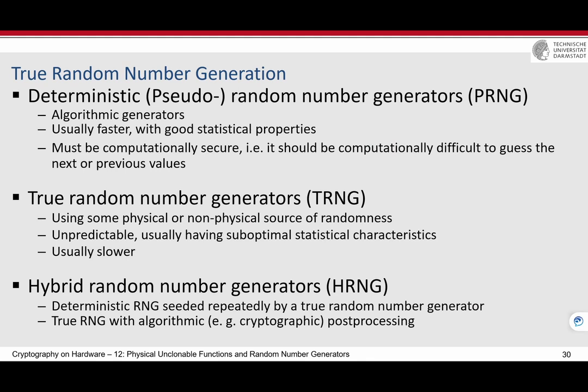There are different specifications of them, deterministic and pseudo-random. For example, you heard about the PRNG, I'm pretty sure. You can use an LFSR, for example, or an NLFSR. We also talked about Trivium before in the lecture. Then you can use Trivium or stream ciphers as pseudo-random number generators. But the problem with true random number generators, as we will see, is that they are very slow. Every time they want to generate a random number, it takes some time with random bits. It means that they don't have a high throughput.